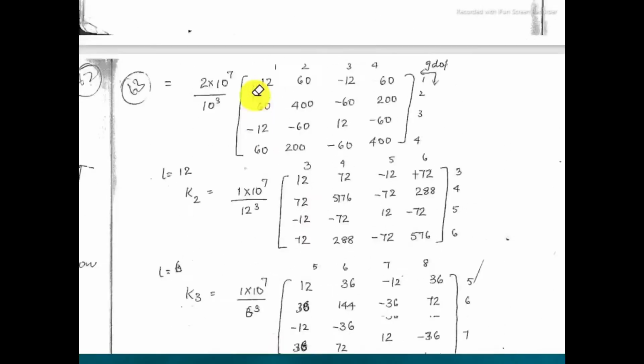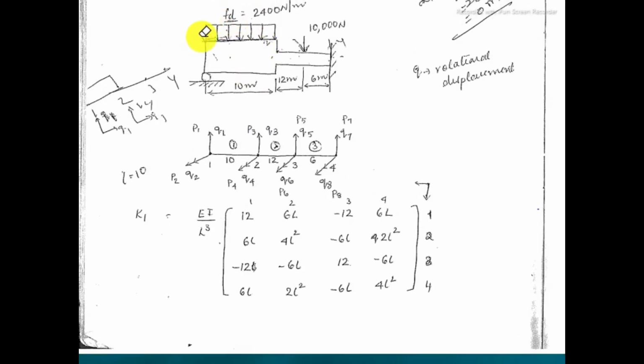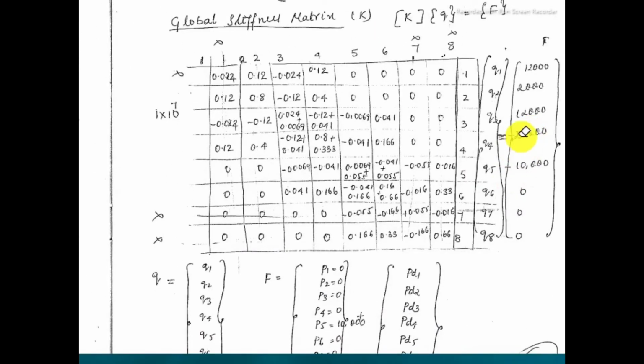It means for the bending moment due to the UDL, when this UDL is acting on the beam, the bending moment at node 1 will be in the clockwise direction, whereas at node 2 it will be in the anti-clockwise direction. So we take plus for node 1 and minus bending moment for node 2. So you have to take minus 20,000. Again here the minus 10,000 is for the point load, it is acting downwards, so minus 10,000 is taken, right?